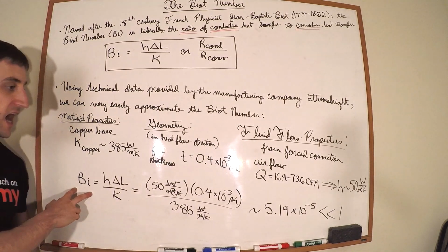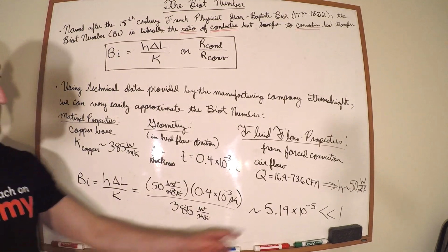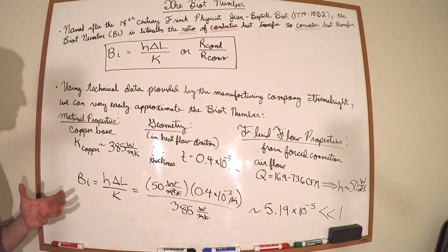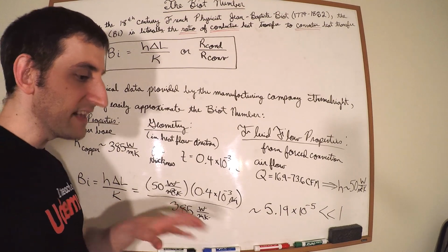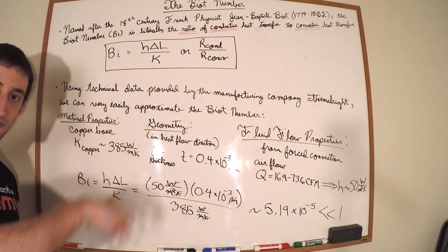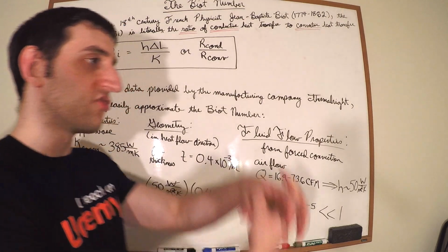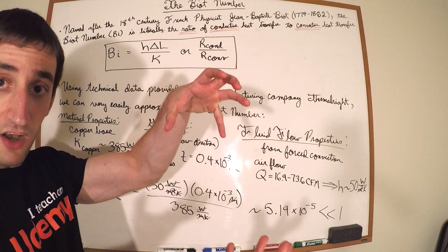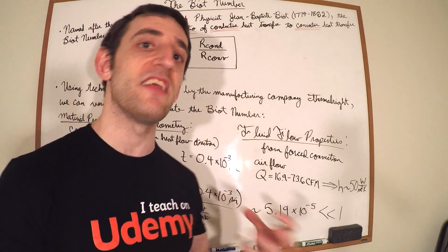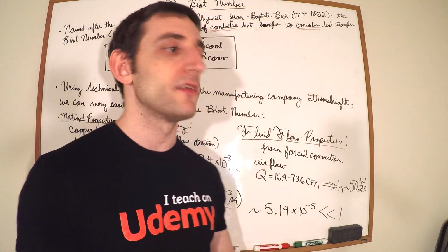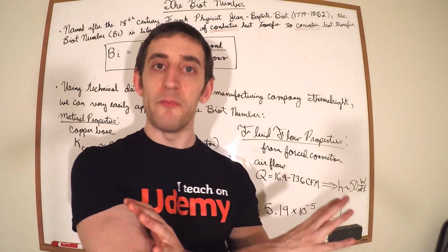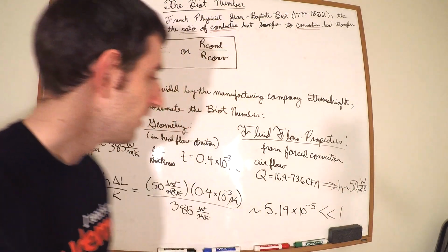We calculated the non-dimensional Biot number. It's much less than 1. It's very small. And so that insinuates that since it's very small, at least in the direction of the fin, that perpendicular direction, heat transfer is going to spread out very quickly due to conduction, but it's going to struggle to be dissipated through convection. In essence, convection is the bottleneck. That's generally what happens, especially with metals. It's easier to flow through metals than it is to dissipate through the air. That's going to be the bottleneck.